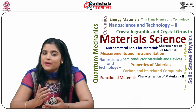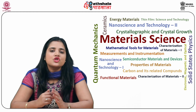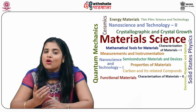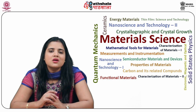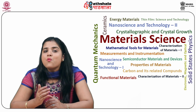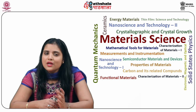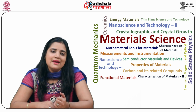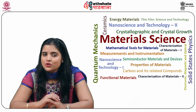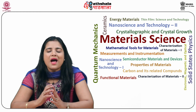This method is based on the use of a number of comparator circuits which are arranged in parallel. Hence, analog to digital converter based on this method is also called as parallel ADC. In general, for n-bit digital output, the number of comparators required is equal to 2 raised to power n minus 1. The analog signal, which is to be converted into digital, is applied at the non-inverting input of all comparators